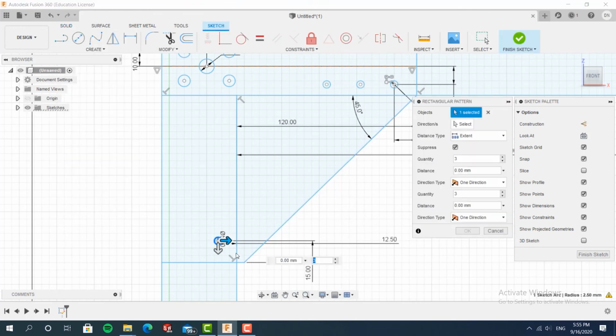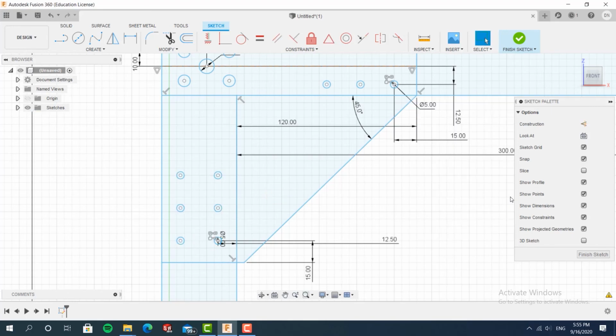The strength of this is in numbers, and the places that you can fit it in is smaller than integrating guides, is smaller than integrating different support mechanisms like just a support beam or flange. That's why it's very useful. Basically, if you see two parts that are close to each other or on the same plane, you can connect those two with a gusset.